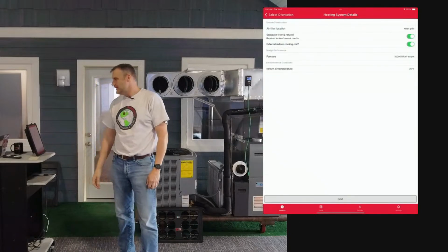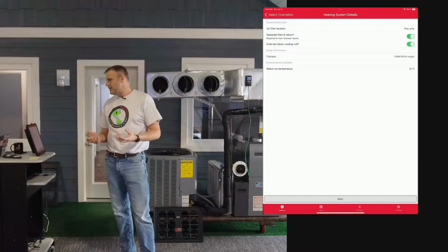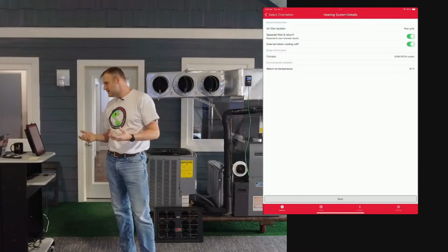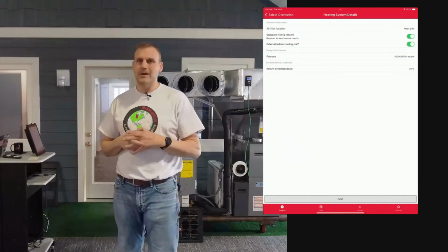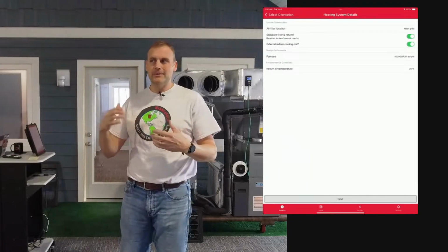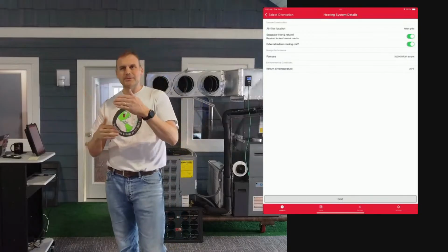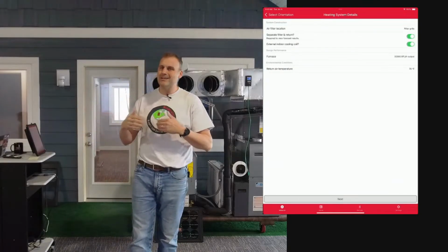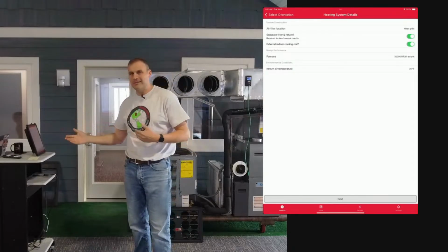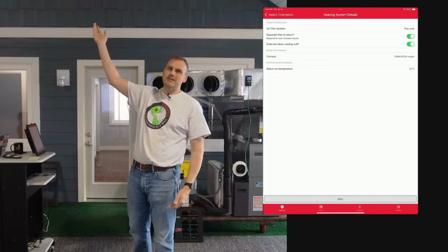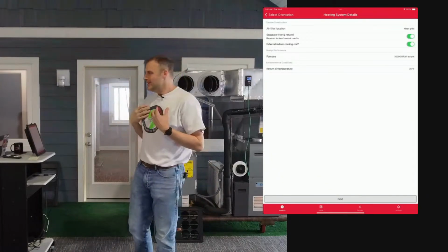All right, so we've got our furnace details entered at this point. Last data endpoint on the detail screen is return air temperature. We're at 70 degrees. That's default. That's what shows up. Here's what I will tell you. I advise people, look and see what's on the thermostat, use that temperature, go with it. A little bit of temperature variation in that input is not going to change flow very drastically. Like if I put in 75 instead of 70, I'm not going to get 100 CFM swing in the measurement. I might get 2 CFM a swing. All right, so don't freak out.